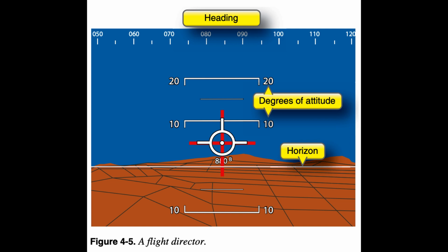Using the flight director, FD. Flight director without autopilot. The FD and autopilot systems are designed to work together, but it is possible to use the flight director without engaging the autopilot, or the autopilot without the FD, depending on the installation.